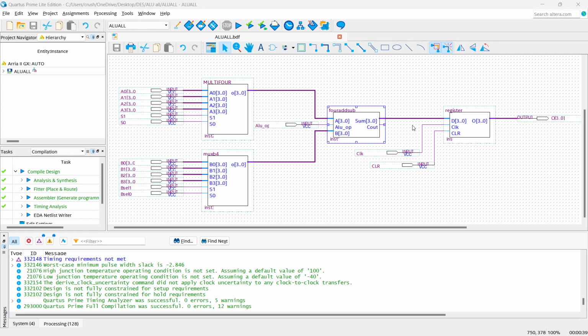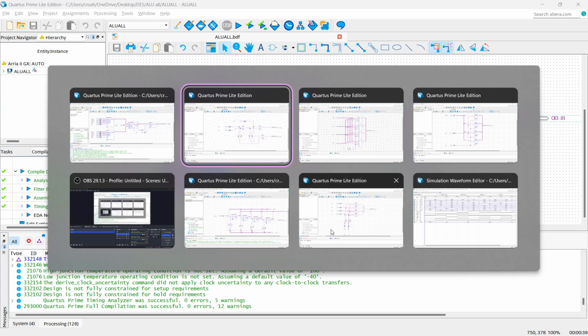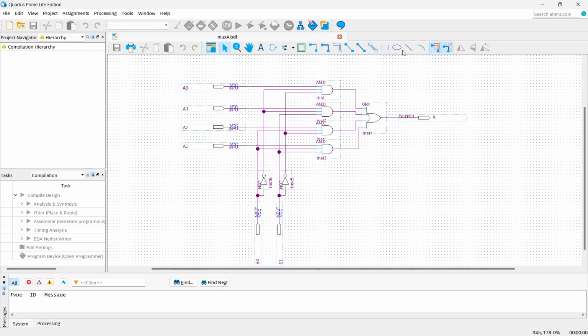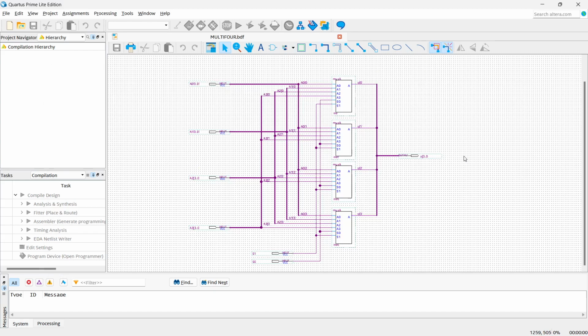So first up, let's look at the initial. This is the circuit diagram for the multiplexer, and then we can represent this as a block and combine it to become a 4-bit selector number, which has 4 multiplexers here, and it will produce an output of 4-bit, which is equivalent to the number that we have. Of course, our number A and B is 4-bit, right?